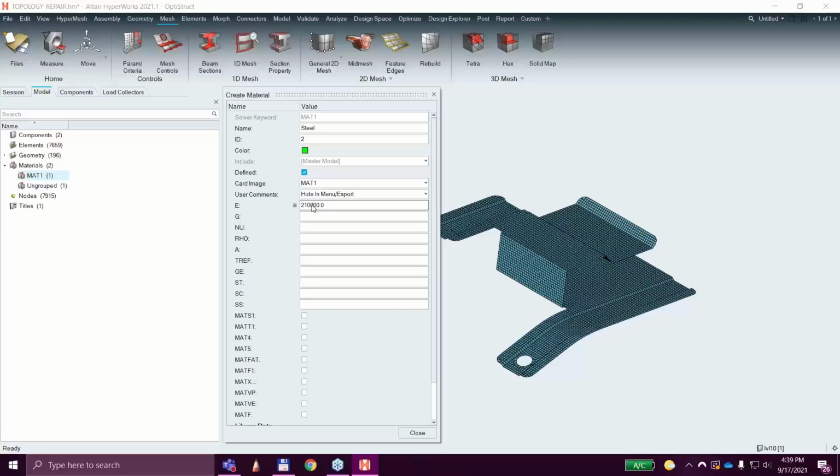I really don't have the time to get into the real in-depth discussion about unit consistency within a software. But when I'm working with a model, I have to define three things: a unit of length, a unit of time, and a unit of force. And the unit of length is decided upon during the CAD process. In this case, it's going to be millimeters. I am going to use millimeters. I'm going to use newtons, and I'm going to use seconds.